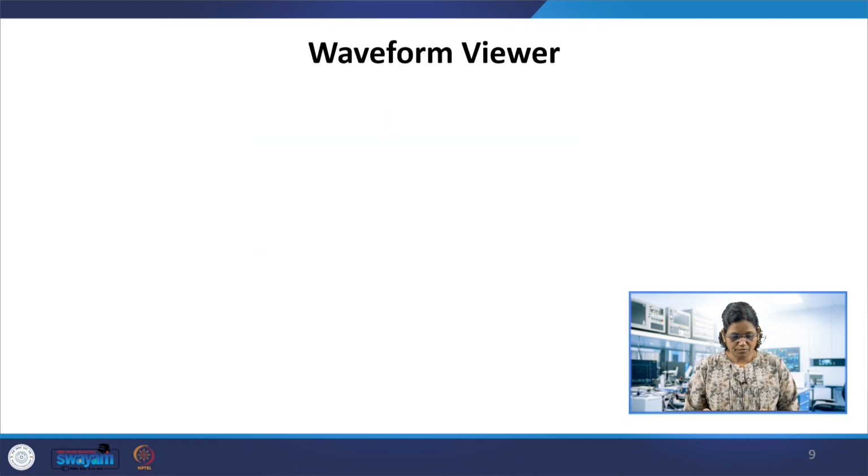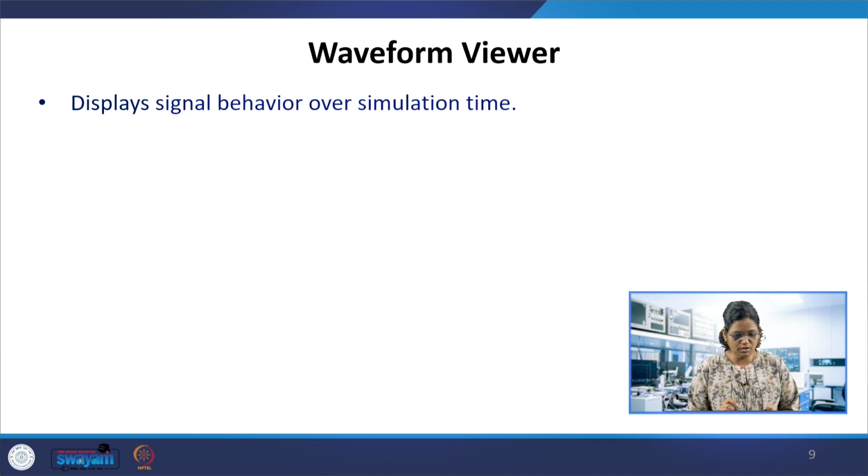And the waveform viewer. The time dimension, the grave accent timescale, time unit, and time precision can also be seen in the waveform editor or waveform viewer. The waveform viewer displays the signal behavior over simulation time. How much time we are running the simulation can be viewed in the waveform viewer or waveform editor.